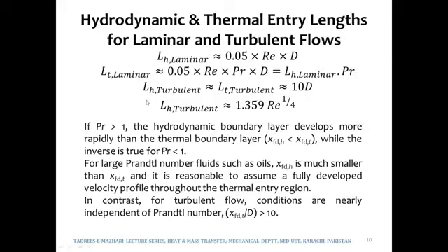Similarly, the hydrodynamic entry length for turbulent flow is approximately 10d, which is approximately the same as the thermal entry length for turbulent flow. And in some cases we can use this expression as well.